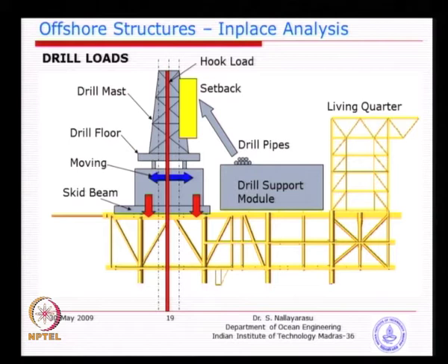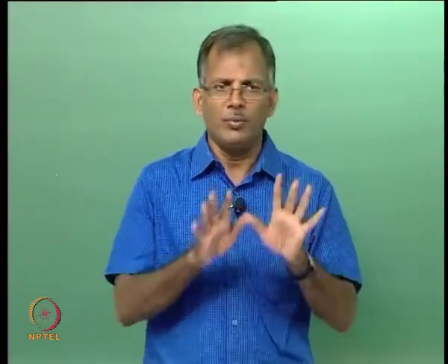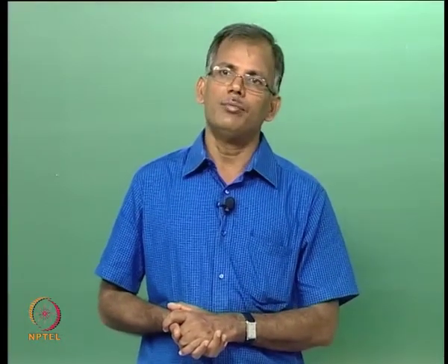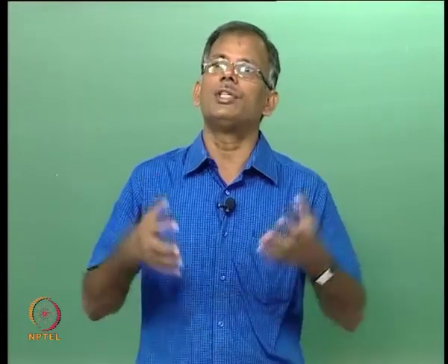Big structure, thousands of elements. Imagine if you have to perform by manual moment distribution method, it may take several days. Of course, it can be done, but it may take several months. That is why nowadays the same method we are talking about, moment distribution method or other methods, a simplified matrix form, we call it matrix method. You know, all principles are similar, ultimately solved by computer, by making a generalized solution for a larger structure.